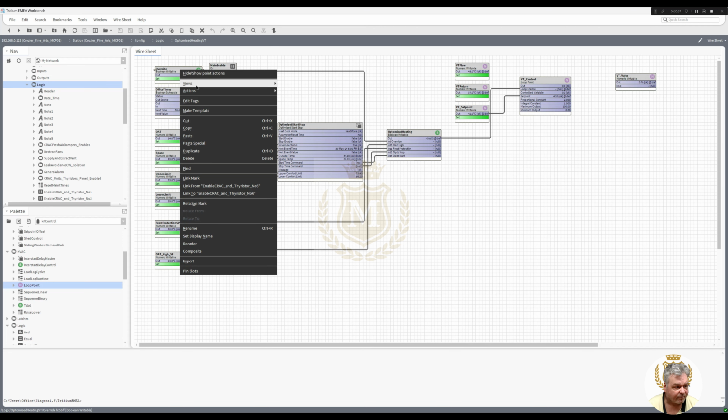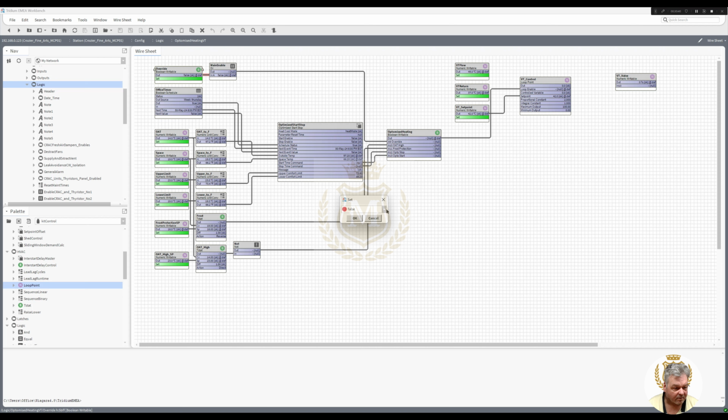We'll override true. So we've now overridden, so we're true. And our control variable, so if we're doing it on flow, that's now winding up for the VT valve. Or we can do it on return control variable, return temperature coming back. So you can either do it on flow or return.